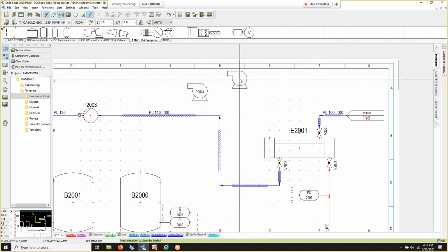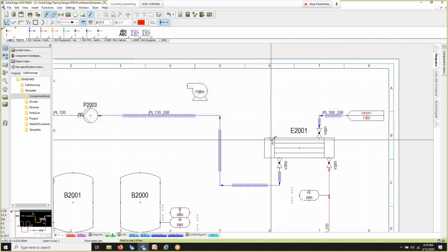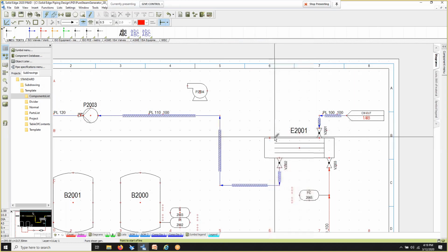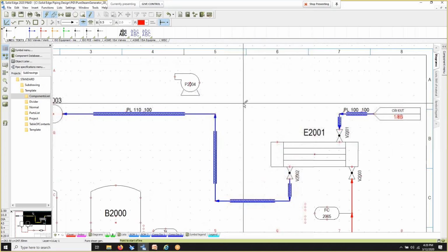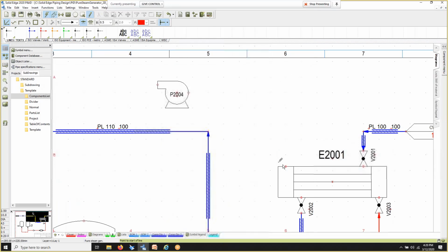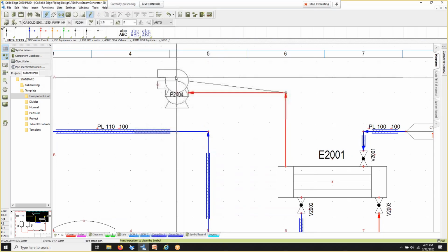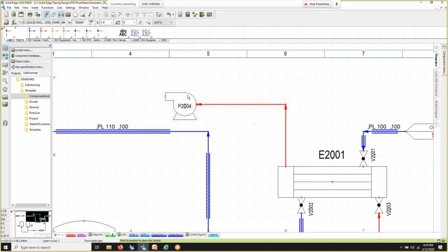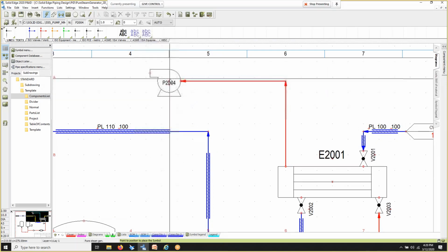So we could conceptually lay things out, and then we could draw a pipeline to say how it's going to be connected. Maybe I want to draw from this heat exchanger. Well, if I don't actually click on the heat exchanger, it's going to know that pipes don't usually float out in thin air. We want to actually connect it to something. So we have these little red diamond shapes that are our connection points. Again, that's a level of intelligence there. Once we connect it, it knows that's normal, you connect a pipe to something else. And once they're connected, they stay connected, even if they cross over other lines and things of that nature.